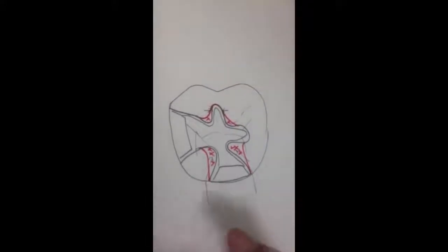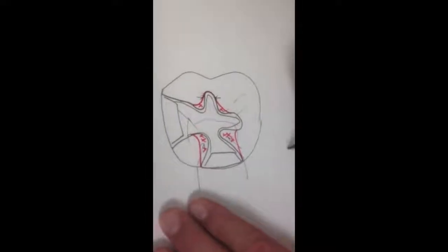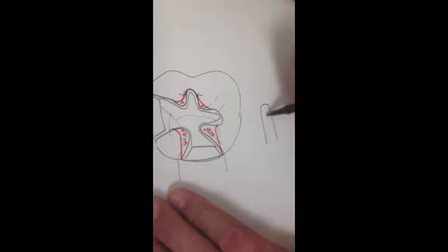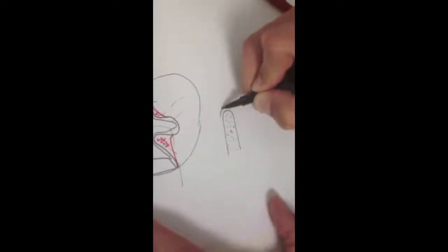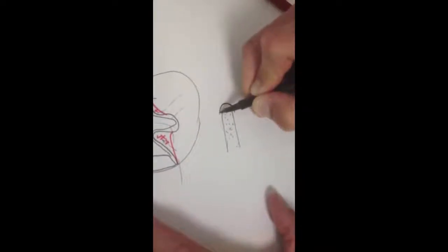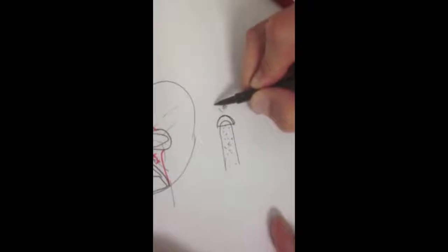The key is the size of the milling burr that mills the restorations, and this is the diamond mill. This diameter at this point is 1 millimeter, okay? And we can't have anything on a preparation that's more narrow than that. It won't get milled. It's impossible.